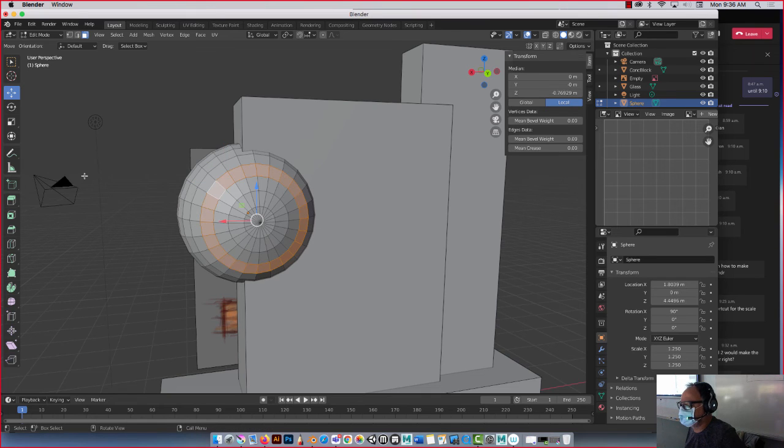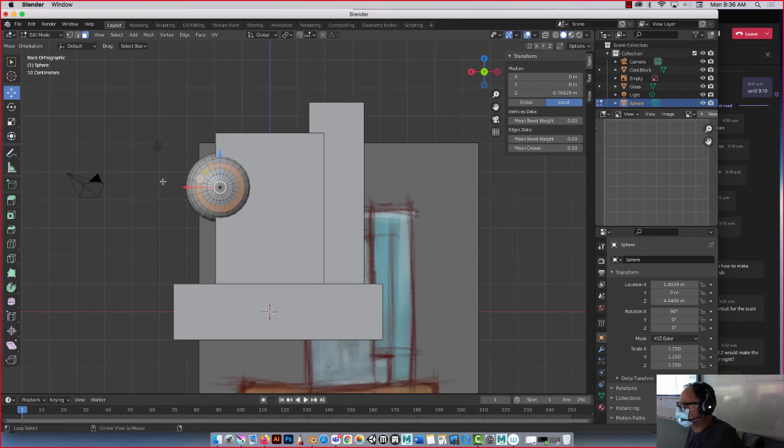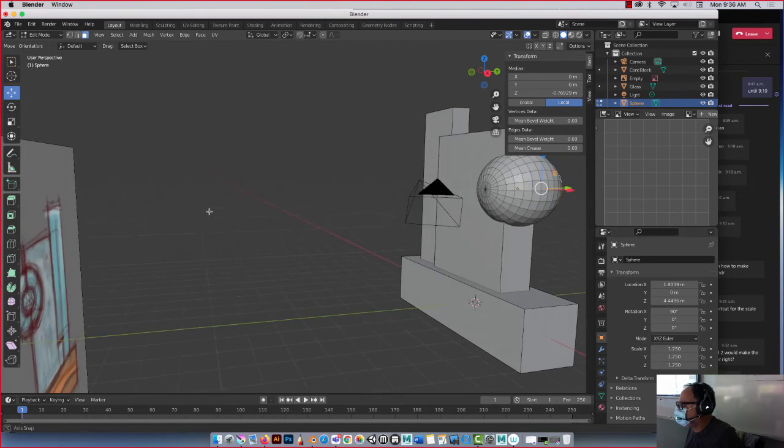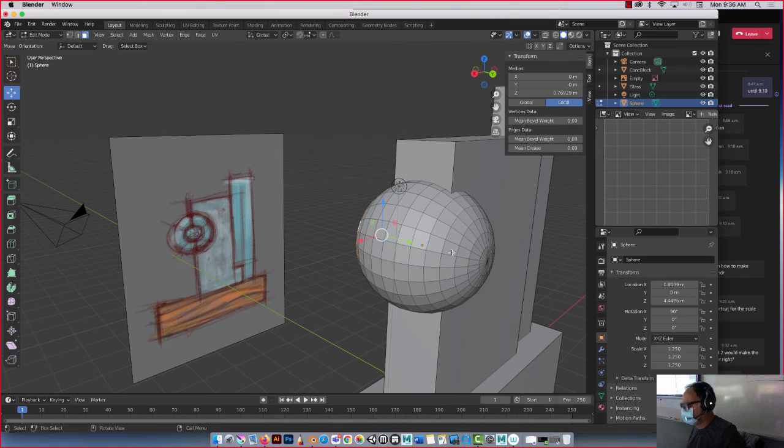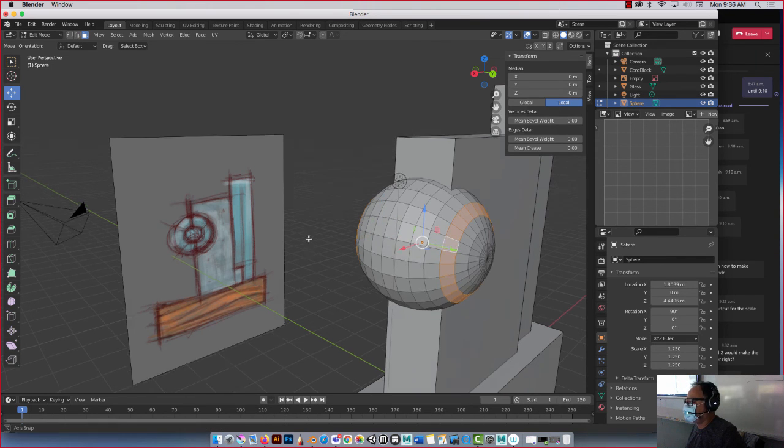Let's go like this. So I'm going to click out, click here. If I want right next door neighbor, hold Alt, left click. There's the loop, right? So this is 1, 2, 3 rings in. So I'll go to the other side. Whoop, somewhere here. 1, 2, 3. Maybe it's this one. Click once. Oops. I'm going to Alt click. Where's my Alt? Right here. There. Okay, and I'm going to Shift Alt click this one. Boom. These two are selected.